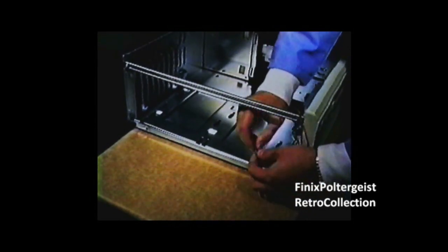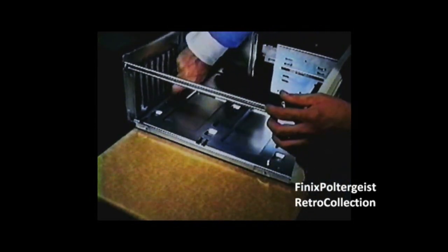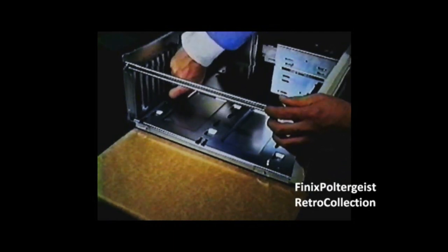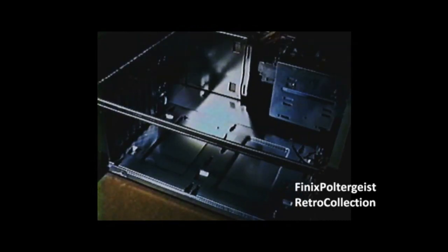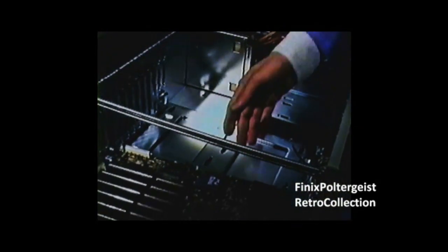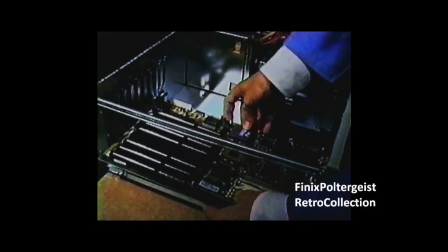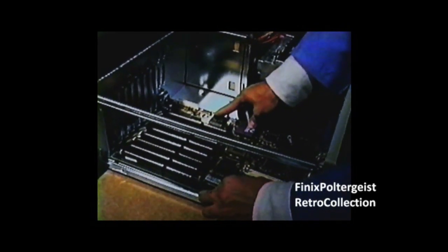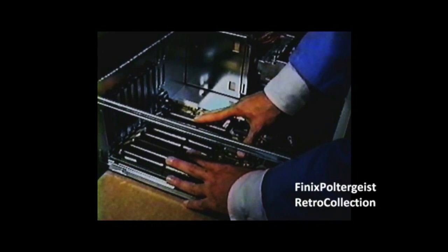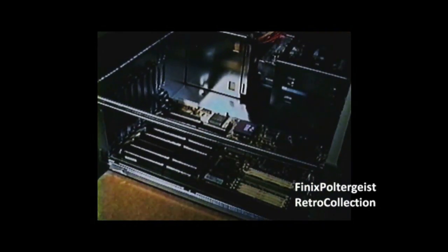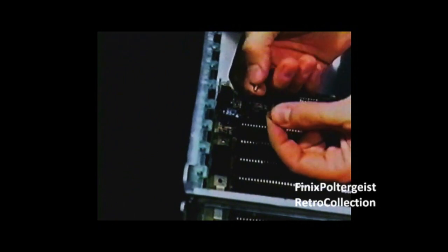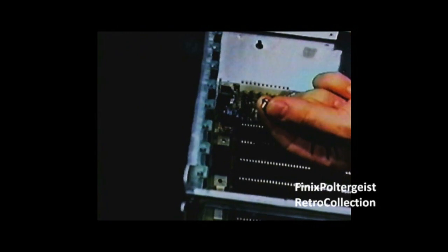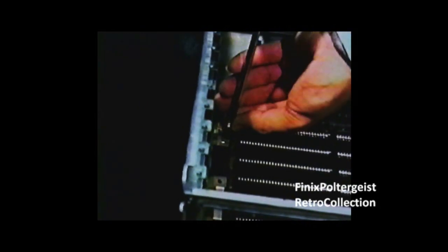Now screw at least 2 brass mounting nuts into the case in positions that will align with the holes in the motherboard. With the insulator installed, carefully slide the motherboard so that each insulator locks into a corresponding hole in the case. Secure the motherboard into the case by installing 2 screws and insulating washers through holes in the motherboard into the brass mounting nuts that you have previously installed.